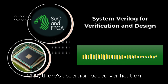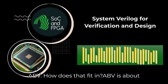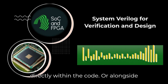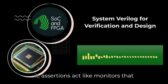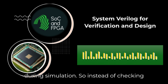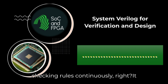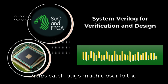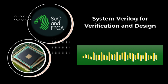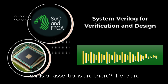Okay, beyond CRV, there's assertion-based verification, ABV. How does that fit in? ABV is about formally specifying expected behavior directly within the code or alongside it. Assertions act like monitors that constantly check if the design is behaving according to its specification during simulation. So instead of checking outputs at the end of a test, you're checking rules continuously. Right. It helps catch bugs much closer to the source, drastically reducing debug time. It's about defining what must always be true, or what should never happen. What kinds of assertions are there?